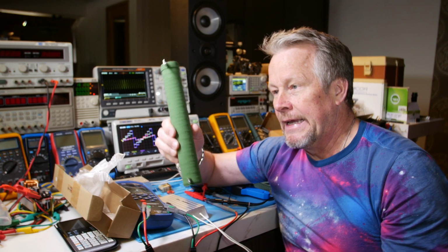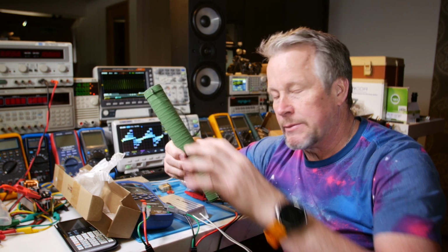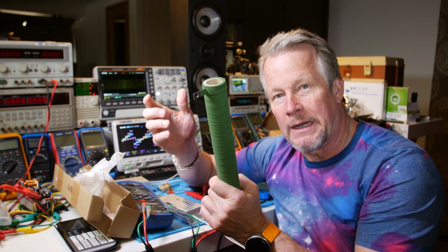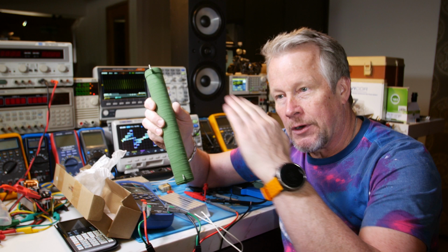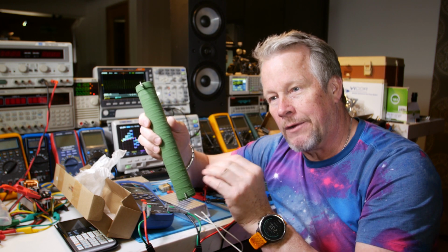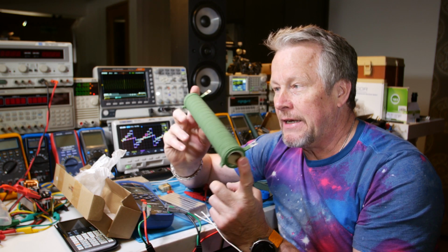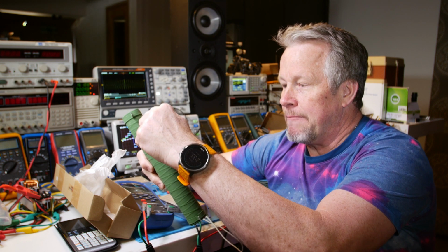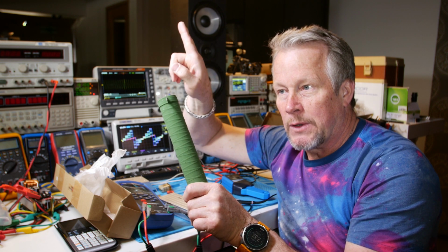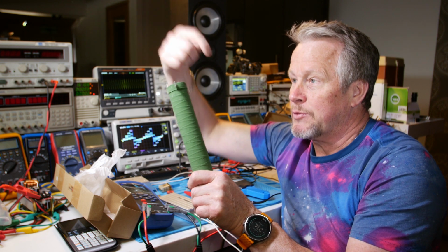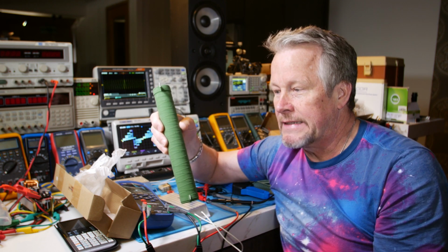And the reason they do that is to make a resistor, they take a certain kind of wire and they wrap it around, and you have so much resistance. Well, when they do that, they just made a coil, right? That's pretty obvious when it's this shape. But even if it's square, if you have current going into a loop, whether it's square or round, you're going to get inductance. And so to make a non-inductive, they take the same amount of turns back the other direction. Now, they have to actually wrap them. So if you go clockwise one way and the current's going clockwise, when it comes back, it has to go counterclockwise. So those two fields equalize and cancel.